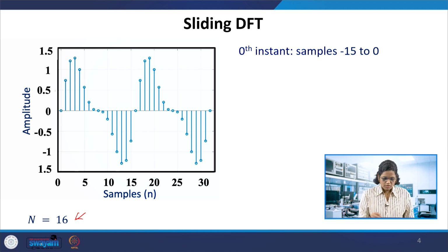So when we are trying to extract this from the signal, suppose we want to extract this fundamental alone. It has a fundamental and a second harmonic. I just took k equal to 1 as the bin index in the DFT equation as an example. If we put k equal to 1, we can extract the fundamental alone. So how are we going to do that?